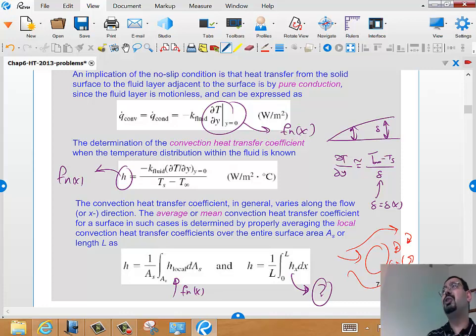But to move it to temperature and conduction, heat transfer, you need to transfer that velocity profile to a temperature profile. And that's where the Prandtl number will show up. So all those formulas will be basically Reynolds multiplied by a Prandtl, multiplied by a constant, to a power of a constant, and those constants all come from experiments.